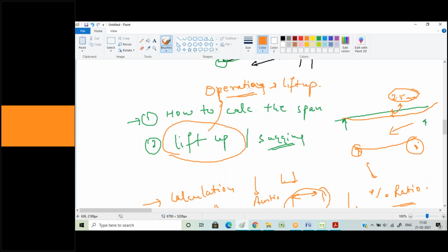If there's a lift up in sustained condition, then you cannot help the cause. Either you put a vertical down support, or you clamp it or do something in order to restrict that lift up in case of sustained loads. I'm talking all this with respect to Caesar. So when there is a lift up of say 2.5 mm or 2 mm in sustained case, this is not permitted. Any lift up above 2 mm or 2.5 mm is 100% not permitted, so you cannot assume this.